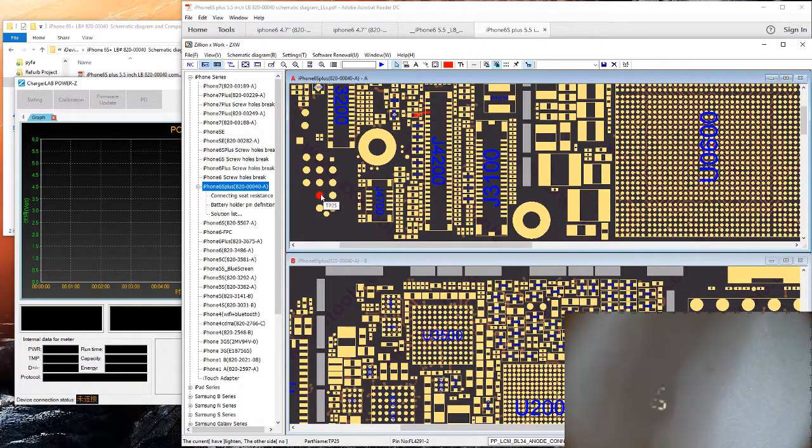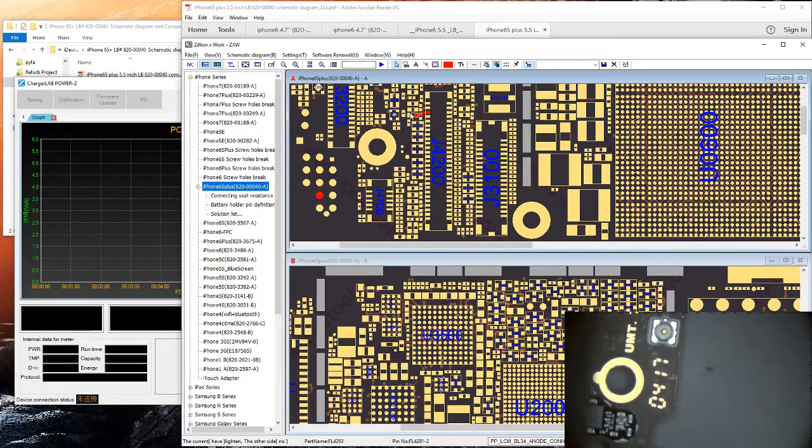So this little test point comes into play in that case, because you can use it to run a jumper wire from, I usually do it from here, run it all around this little way, route it that way, put it here, then you can put a filter right there, so it's still a filtered connection.